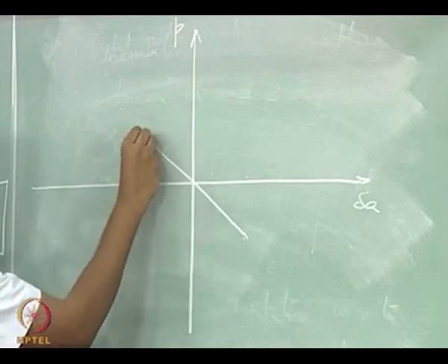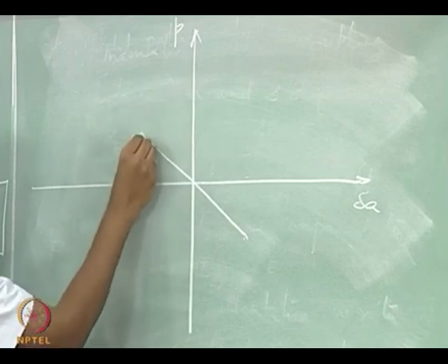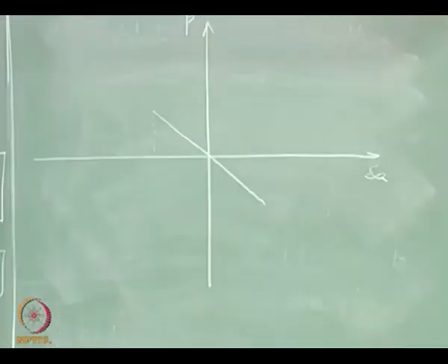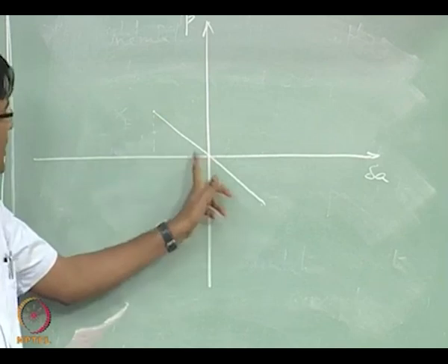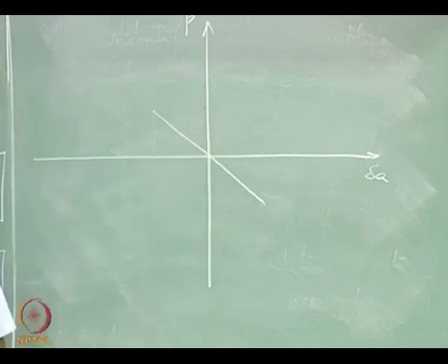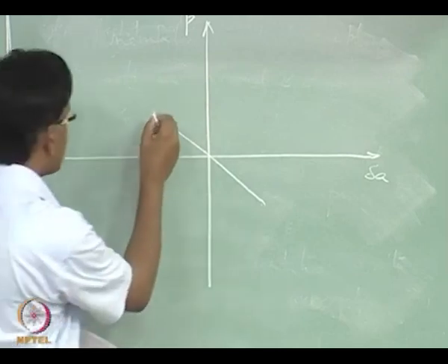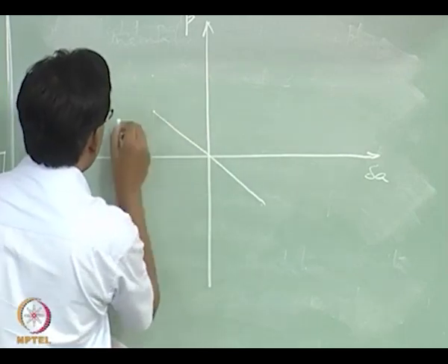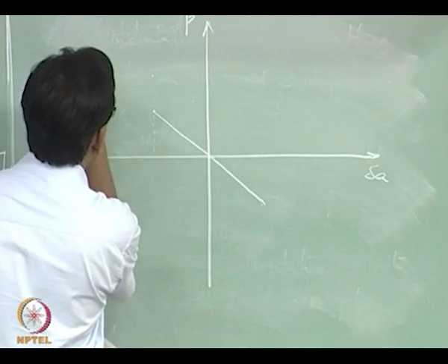Suddenly you see that your aircraft has jumped into a situation which is giving you higher roll rate than expected, right. So you would expect this linear growth of roll rate when you are deflecting your aileron, but that does not happen, and what you see is a jump in roll rate.